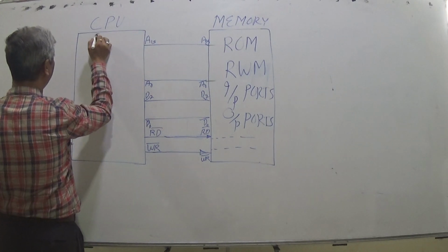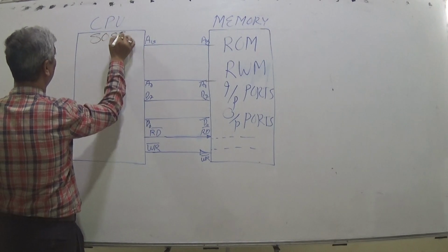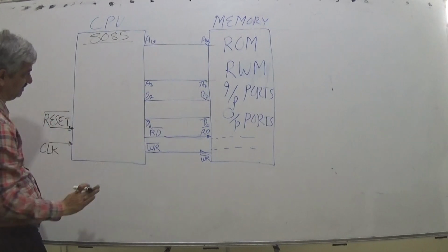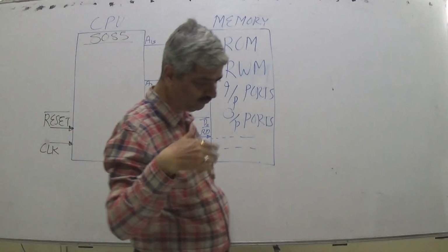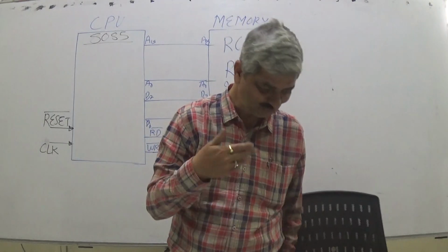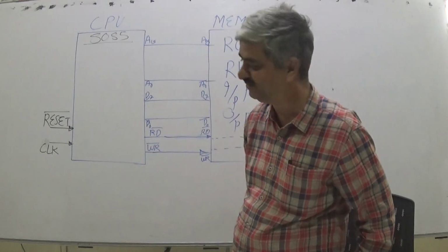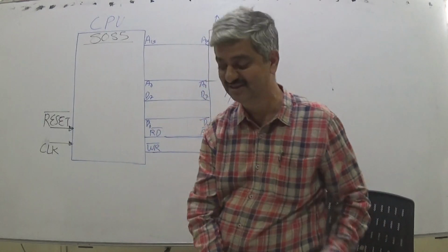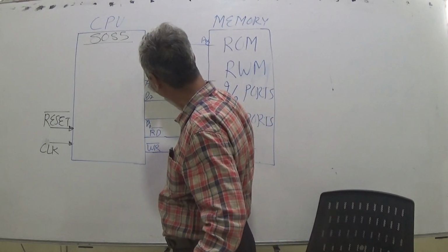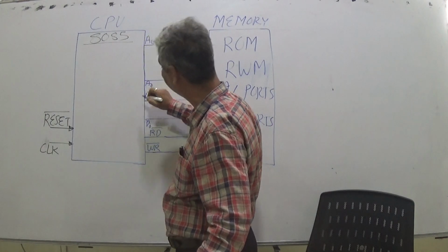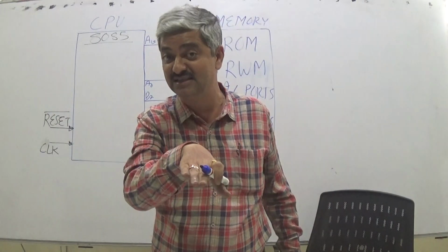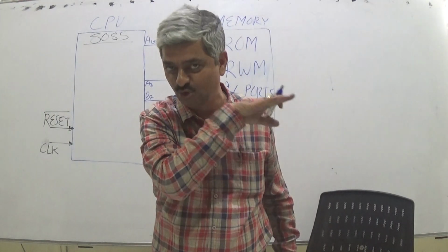We will use 8085-like examples when we take the register names, pins, etc. Those who have learned vocational 12th or those in CSE or those whose parents are in this electronics field should keep in mind that this is 8085-like. Otherwise you will say, what nonsense are you teaching, 8085 does not have separate address and data lines. It has address-data multiplexed lines. All those complex things I am avoiding because learning 8085 is now no longer a skill.